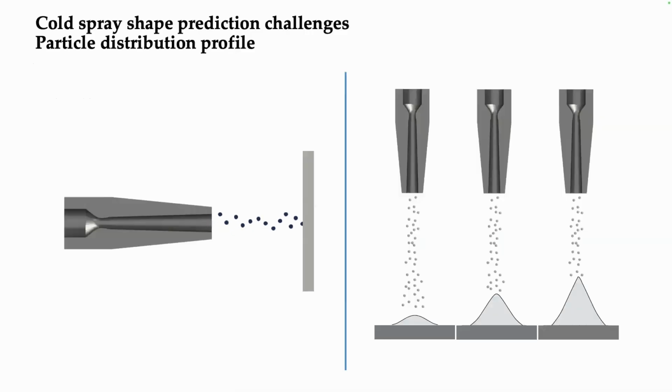The main reason is that when we are depositing on a spot or on, let's say, a straight track, the unit shape of this cross section has an irregular shape that could be approximated by a Gaussian function. So it's not a very regular shape that could be easily superimposed in order to control the shape.